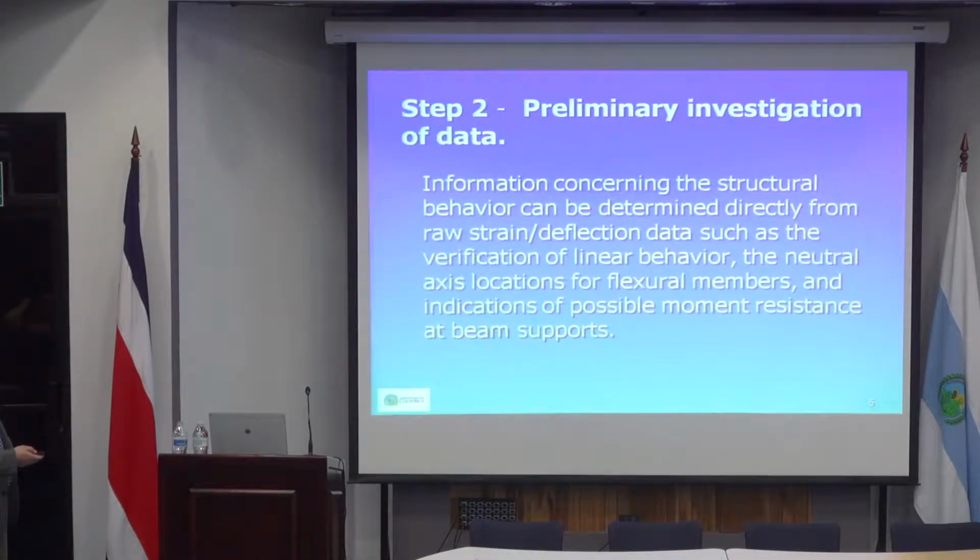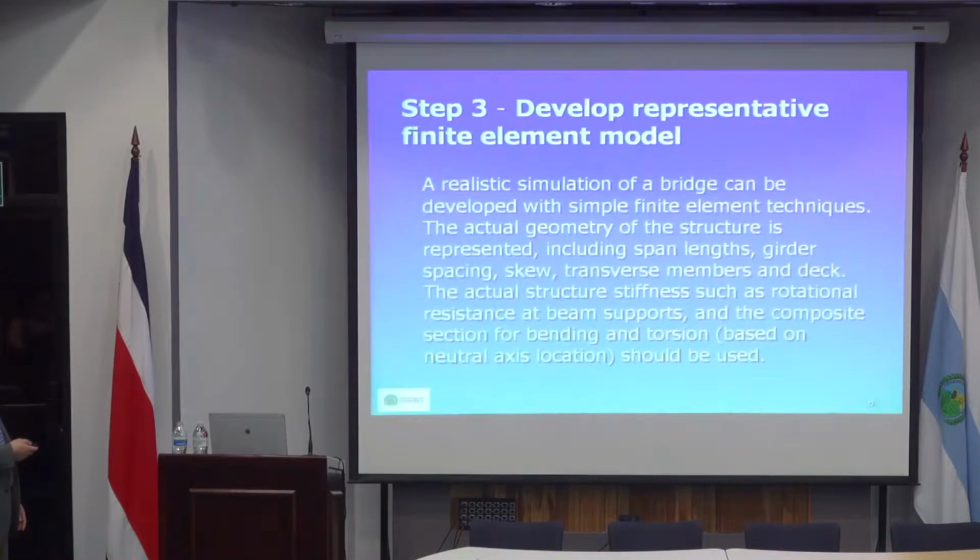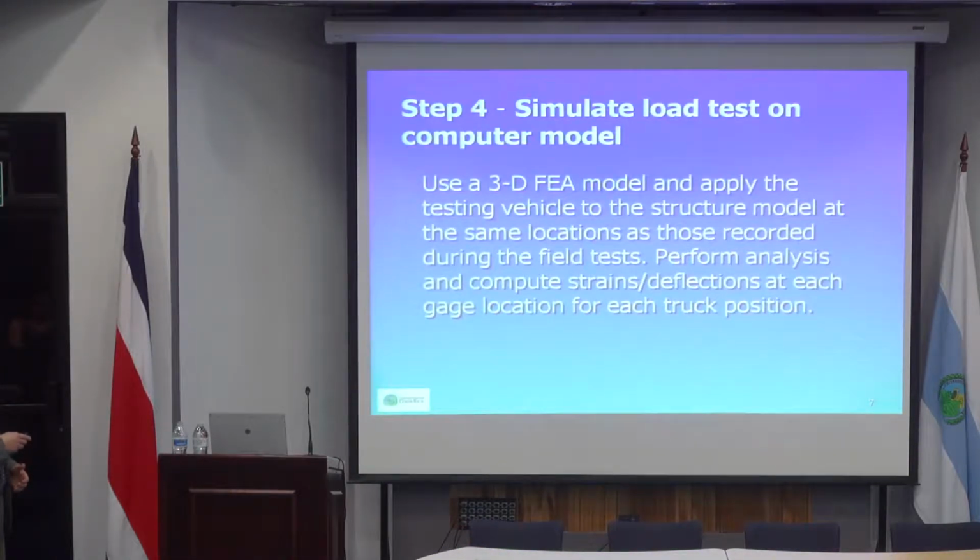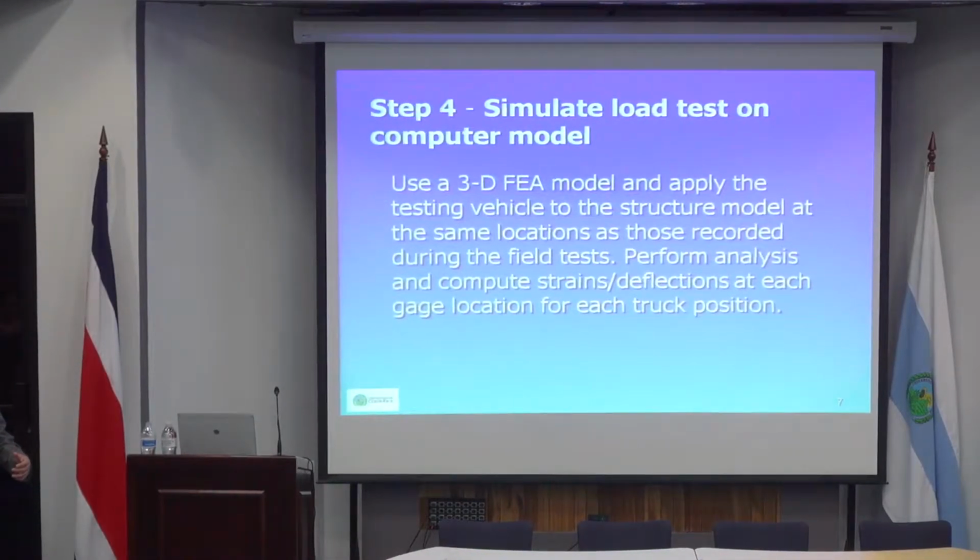Step 2 is to do a preliminary analysis of the data. For example, you look at the measured strain to see how much of the concrete deck should be part of the composite section. And then develop a finite element model based on the initial, original design. Then you analyze that and simulate the actual load data.